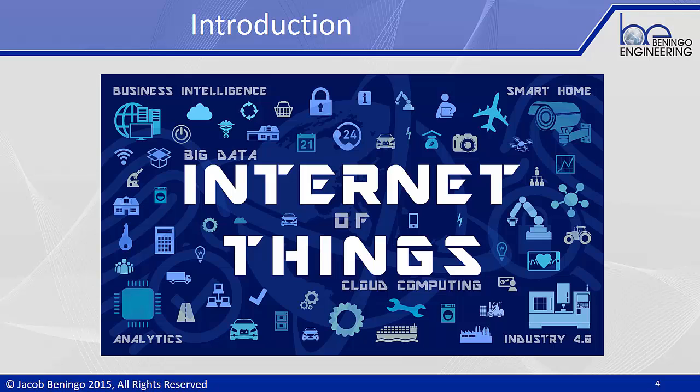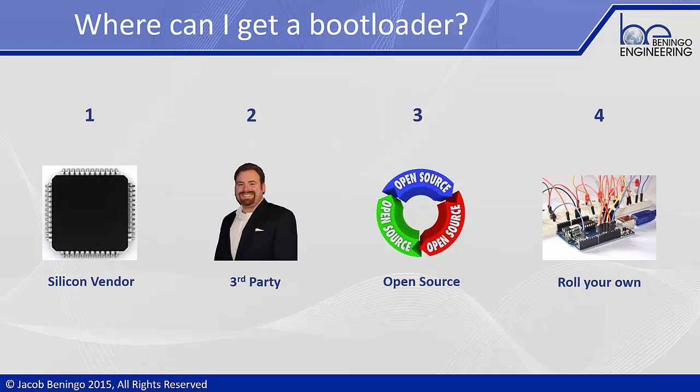Now, as I've mentioned, a bootloader is basically an application whose primary purpose is to allow a system software to be updated without the use of a specialized hardware tool such as a JTAG programmer. A bootloader can also be considered to be a piece of software that boots the system into a known state and can then make a decision on how it should boot from that standpoint on. For our purposes today, we're considering the bootloader to be that piece of code that's going to update the application code in the field.